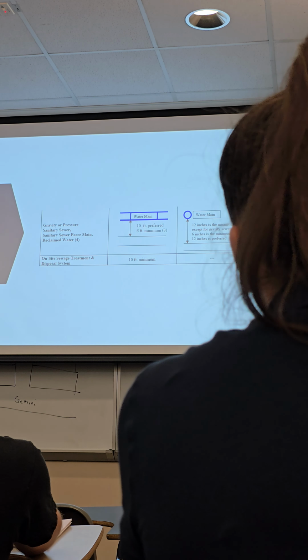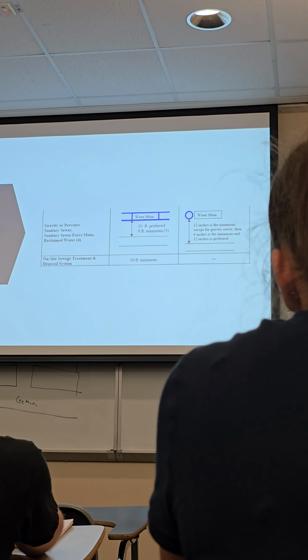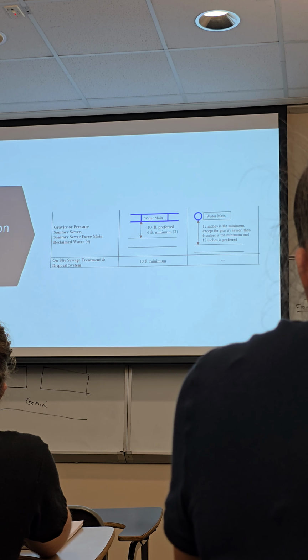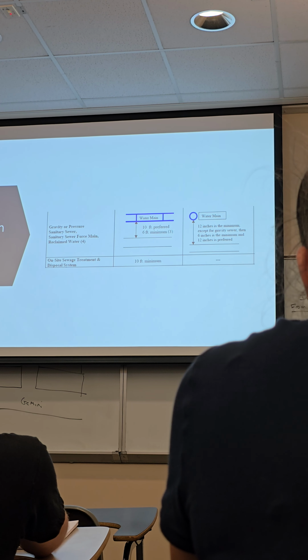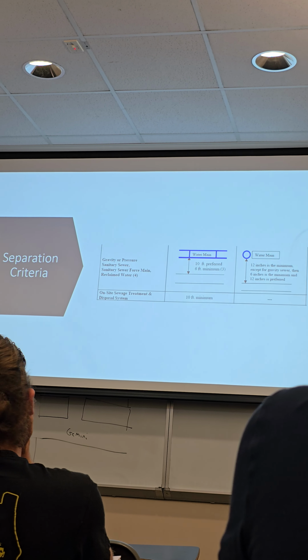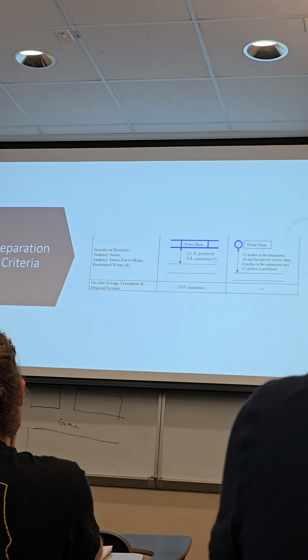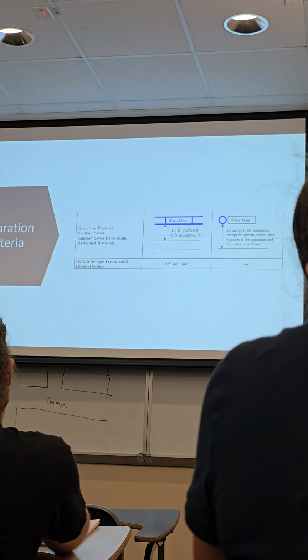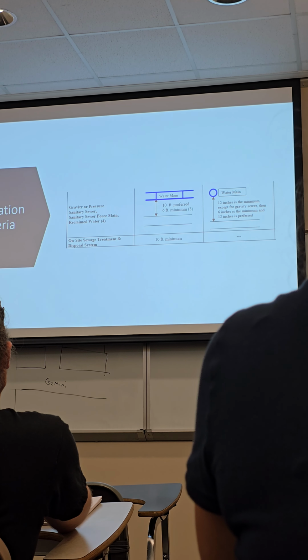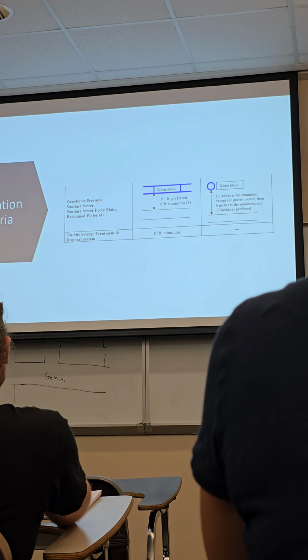So with utility systems, and when I'm talking about utilities, I'm talking about sewer and water mainly, with storm. You want to typically have some separation between them, okay? And the most critical one is water. If you think about water, you always want your water system above the other utilities, right?